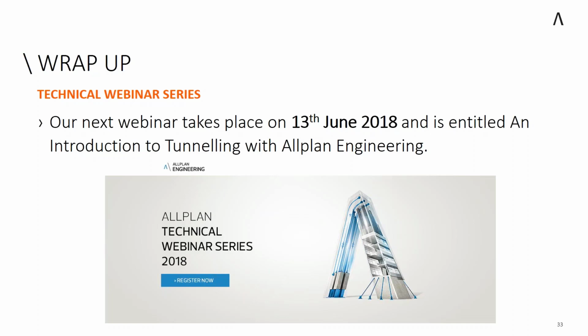I would not suggest to anybody to create information from interpreted results. So I would never suggest to create a digital terrain model from a set of contours, for instance, because contours are derived from the terrain. So you are instantly introducing assumptions into the design. If you're happy with those assumptions and know of those assumptions, then fine, not an issue, not a problem. That is your decision. It is not something that I would personally condone or even use, to be fair.